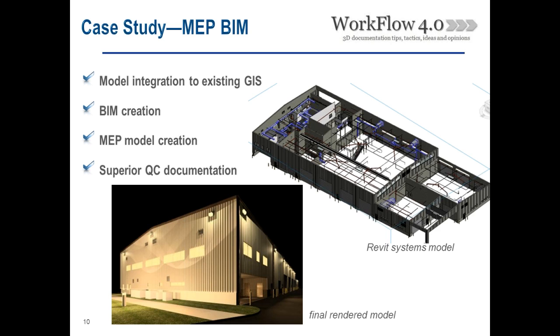That made an interesting problem, because each one of these buildings now has to have a local translation set up through the GIS control network. So we had to do a little planning on how we were going to get each one of these facilities truncated into an environment where the rotation and everything else was consistent with what the control said it was, and then be able to model it and move it into a GIS world and maintain that orientation in the correct position.